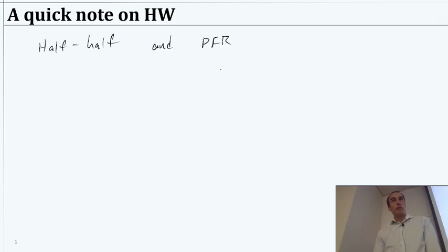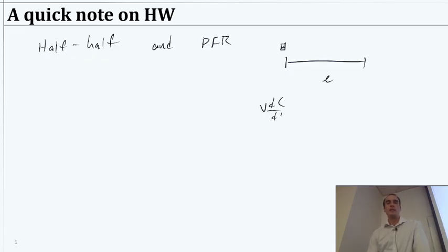Now, a plug flow reactor, first of all, we are going to treat as if we have a batch reactor on some conveyor belt, and it takes some amount of time to get from the start to the finish, right? So if we think about a plug flow reactor that has some length, we're going to treat some infinitely small little batch reactor there. And I say batch reactor because we did the kinetics with a batch reactor, right? V dc/dt equals plus or minus k c to the nth power. That was our batch reactor starting point, and we'd say that's in some volume.